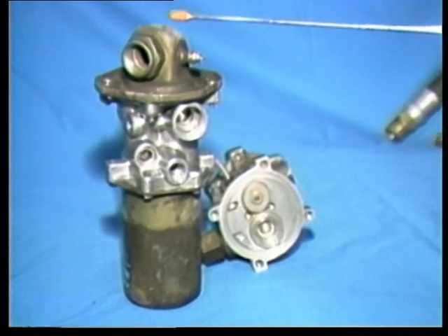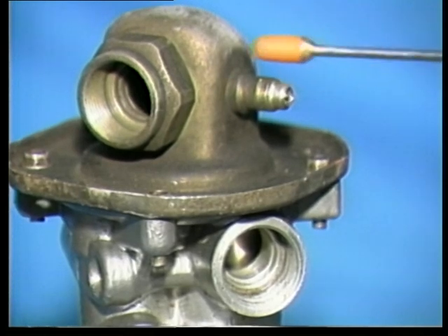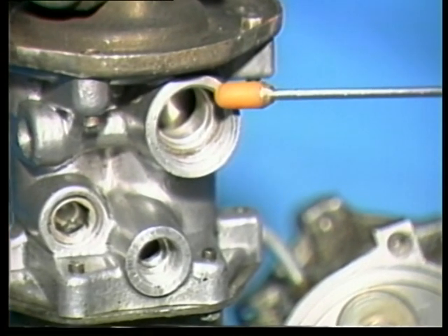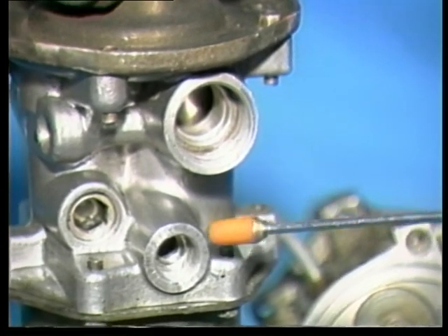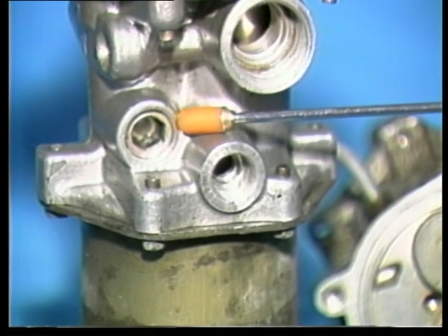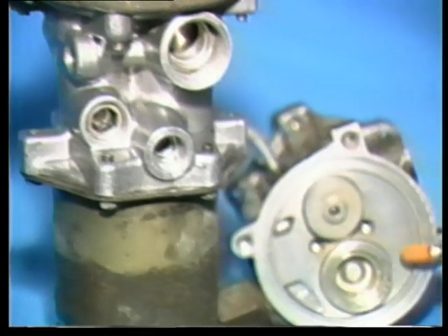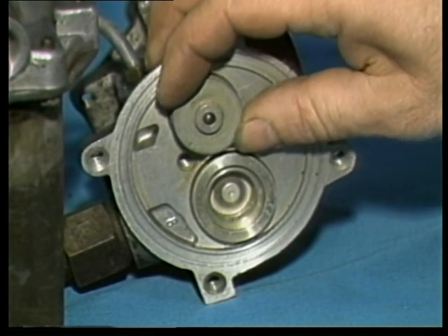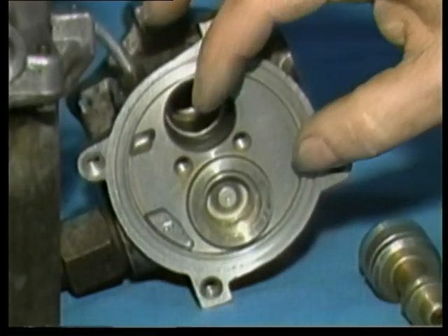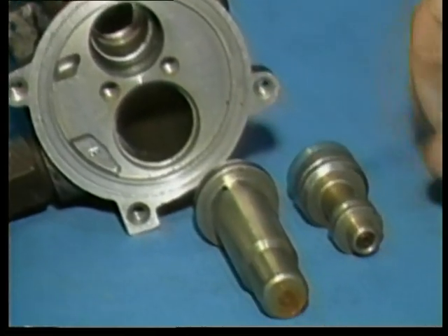This is a VIR, or valves in the receiver assembly. It combines numerous components in one device. It contains a service valve fitting, 3 line fittings, a sight glass, the expansion valve, pilot-operated absolute valve, and a receiver dryer, all in one assembly. This is the expansion valve. This is a POA valve, which senses evaporator pressure to help control system temperatures.